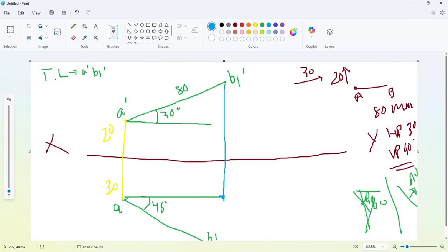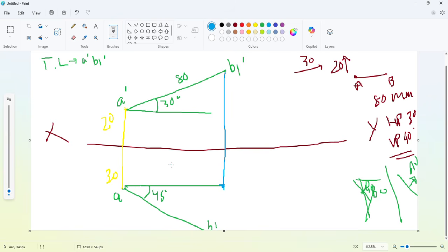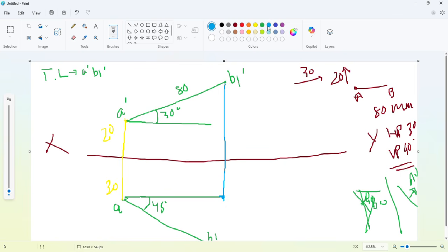Now take this as center. Before this, you have to do one more thing: you have to create the locus. So this is going to be the locus. Now we know the end point of the apparent line after applying both conditions. The view which we get in the VP will be the apparent line or front view, and similarly we will get the final apparent line in the top view. Both these views have their endpoints on the same horizontal line, or locus, of this line.